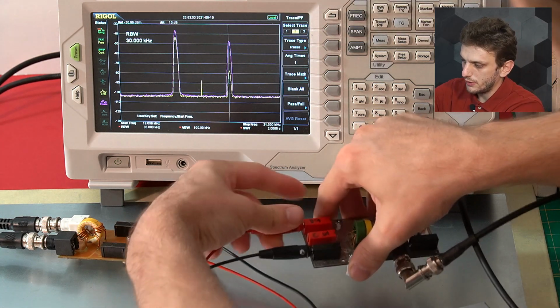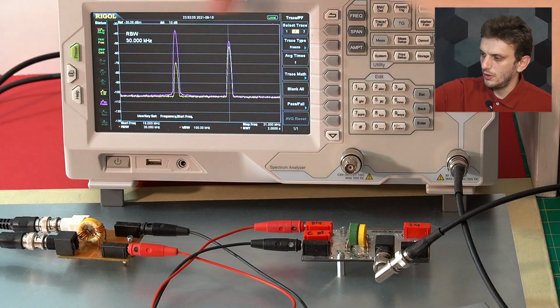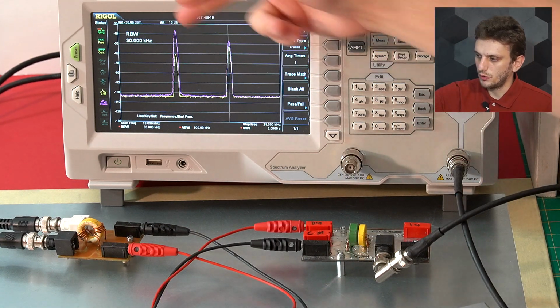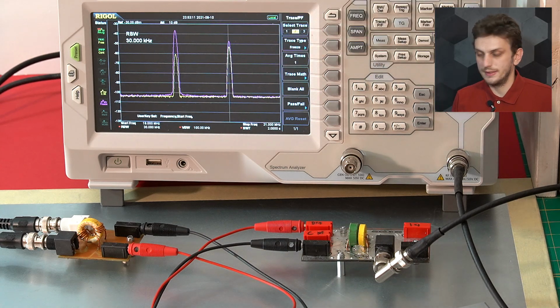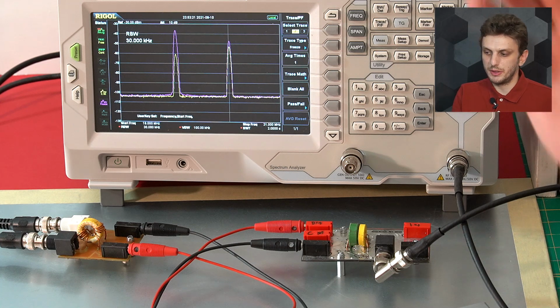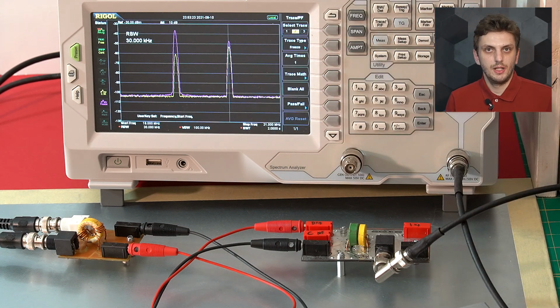And if I swap around the two inputs, we can see the story changing. So our common mode spike has a larger attenuation, our differential mode spike has a smaller attenuation. Now, it's not as great as we had with our low frequency spikes, but part of the issue here can be with the noise mixer itself. So it doesn't work that great at higher frequencies.